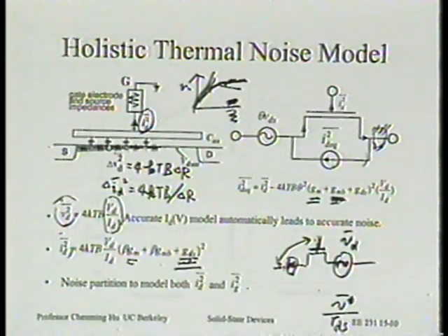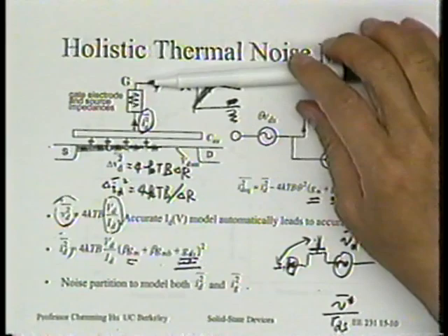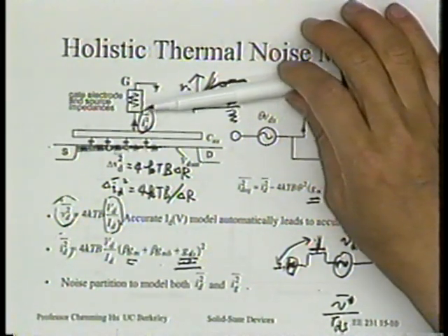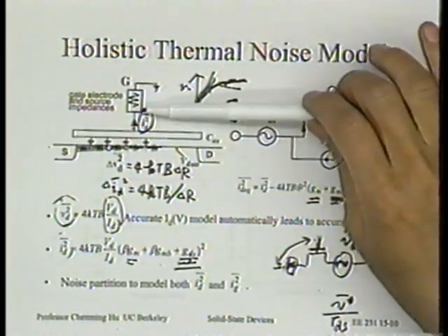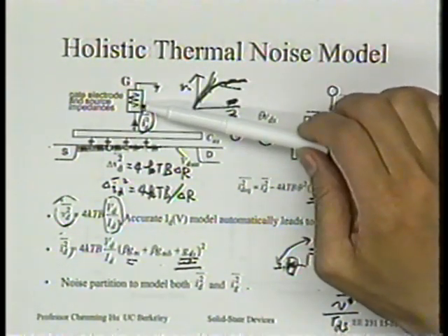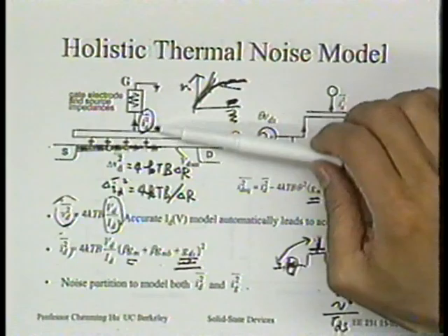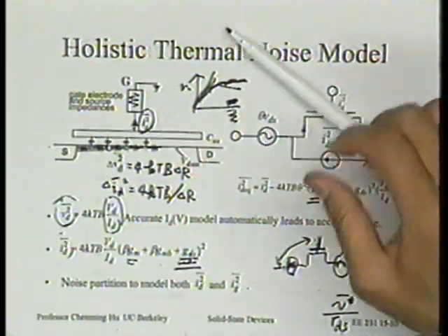So let me first ask you one question. If you can answer that question, I think you really got this totally. Earlier we said there are two components of resistance in the gate. One is the gate electrode resistance, one is the channel resistance. Do you think both resistances should be used to multiply this induced gate current in order to calculate the gate voltage noise?